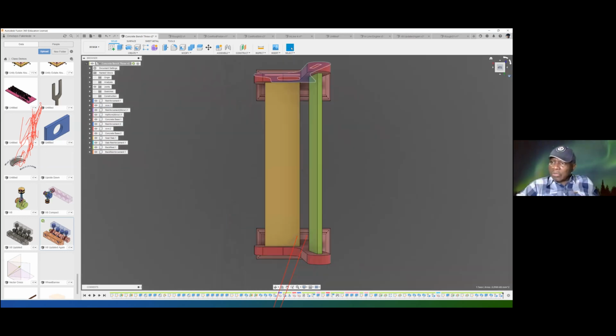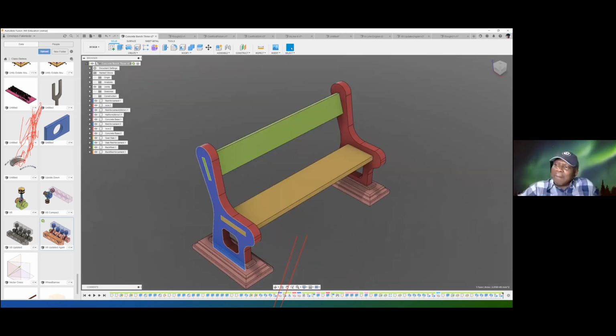And then you can set things. In fact, you can decide to set your current view as front. You can name your views, and you can also set a view as home. You can also take a view and set it as home. Once you set that view as home, many times you press the home button here, it will return to that view. So it is for you to select what view is home. You can do that by looking at the drop-down menu that comes from the view cube.